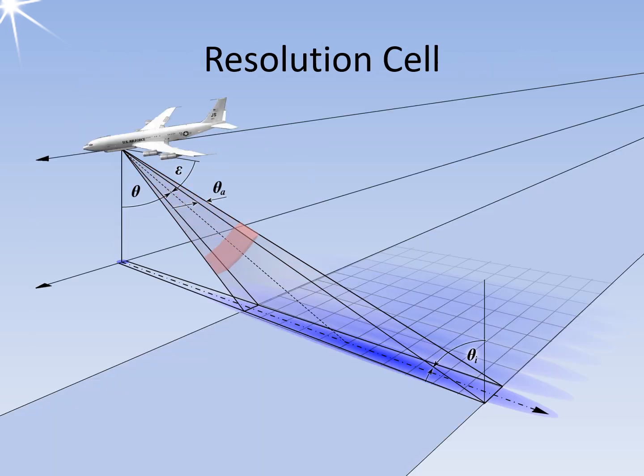The two dimensions of resolution produce areas on the ground that are limited by the minimum pixel size in the flight direction, angular resolution, and perpendicular to the flight direction, in terms of distance. To ensure that these pixels are approximately square, the flight speed, pulse duration, and pulse repetition frequency must be matched to one another.